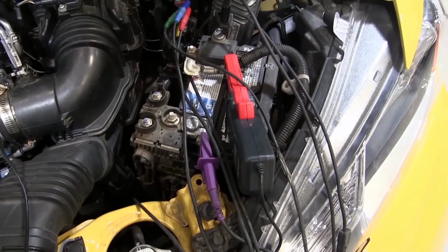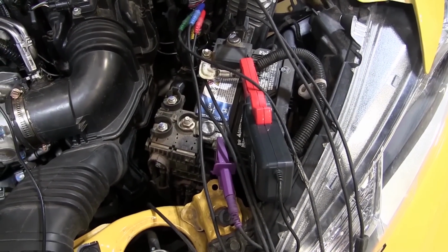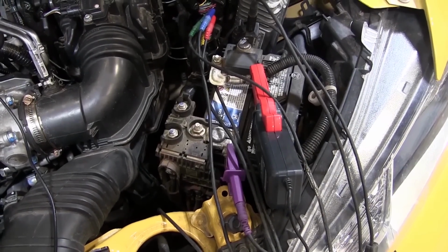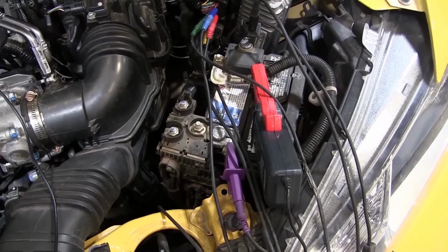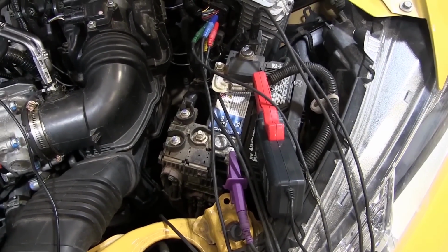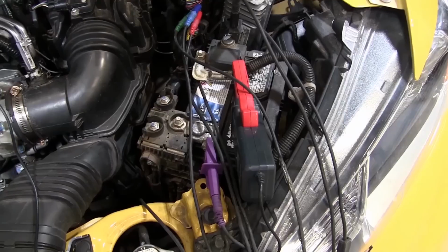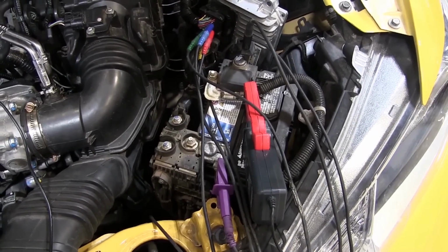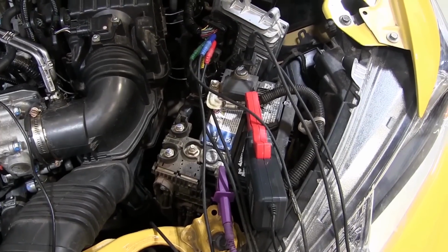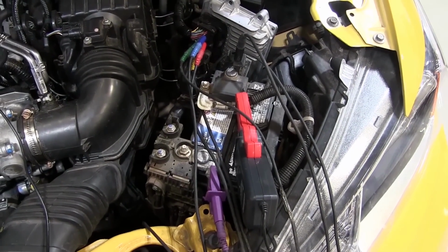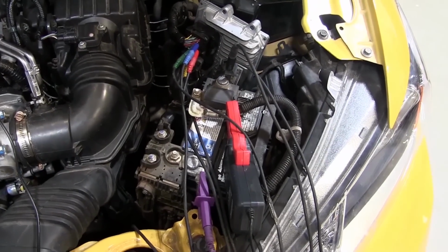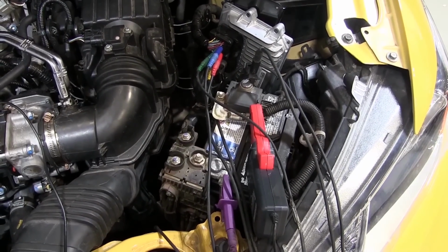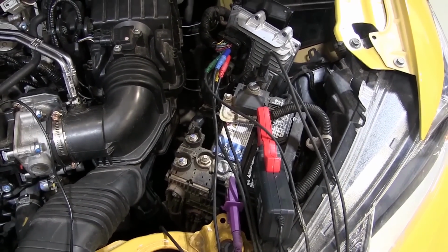And then I always like to have an amp clamp on the powers or grounds somewhere, so if something's pulling really high current and I pull all the current away from the computer and it can't operate the gates properly, I can see that very quickly. So it's always good when you've got a computer style problem to have some type of an amp reading off of it. I've gotten burned on that in the past, and I've learned that I always put an amp clamp on when I'm checking powers and grounds, so I can make sure that there's not some huge current draw going somewhere that won't allow the gates in the computer to operate correctly. So that's where we're connected. Now let's go look at the powers, guys.